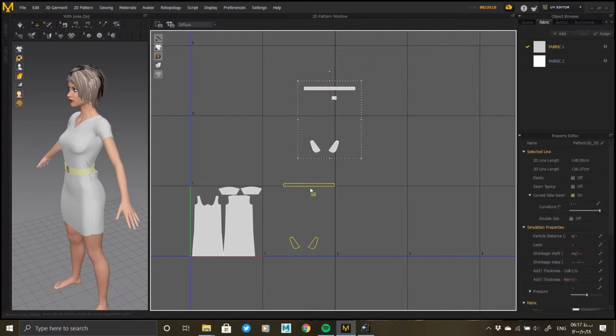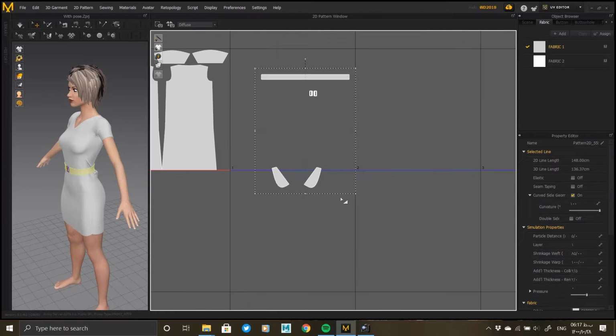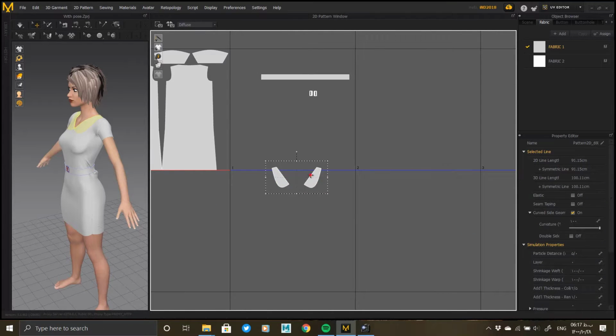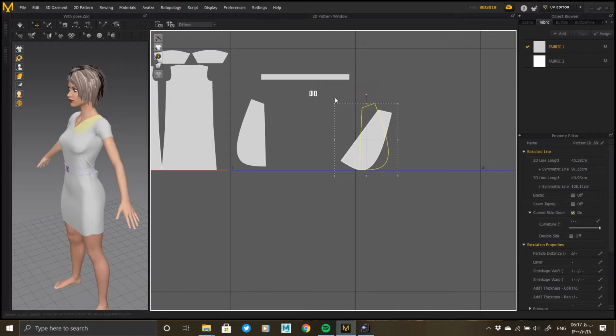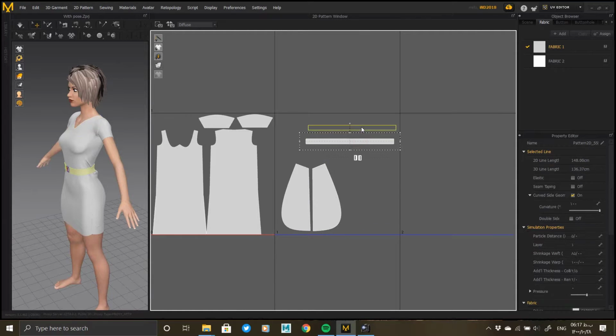The larger the clusters, the more UV space they take up, and the higher the quality of the material. Try to adjust the clusters so that they are as large as possible in UV. If it is necessary to have several clusters of higher quality separately, we should increase the size of these clusters, and it is better to choose parts that do not need high quality, and reduce the size of their clusters. There should be more space for the rest of the clusters. This method optimizes the system, and gives higher quality textures when making materials.